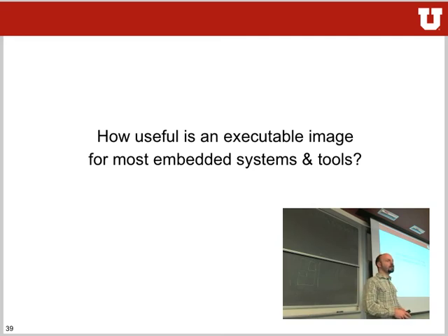Because that's really what's getting uploaded into the flash memory, where everything starts. Yes. These executable files are really important for debugging, because without them, you don't really know what's going on or what the different C instructions mean. So the executable file is really the link between your C code, your assembly code, your source files, and what's written in your binary file later on.